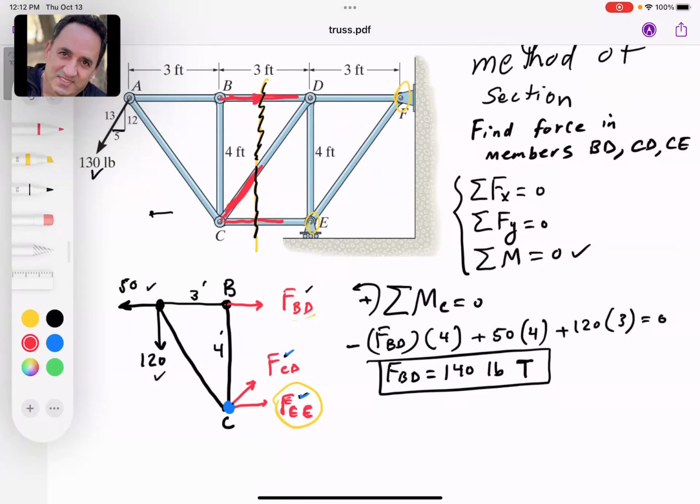All right, so if you want to use your moment equation, take moment about a point where these two other forces are intersecting. So you can actually take moment about, you see this, how these two guys are intersecting at point D here. So that's the efficient way of solving this problem, by taking moment. I mean, for member CE, take moment about D, say it equals 0.